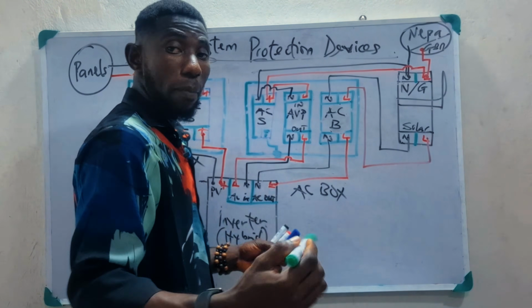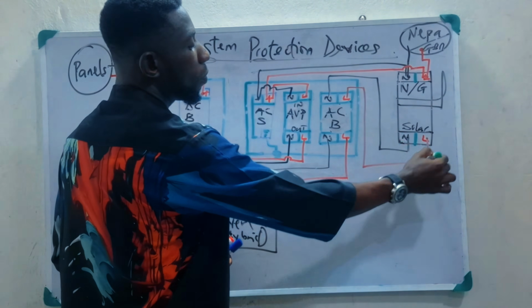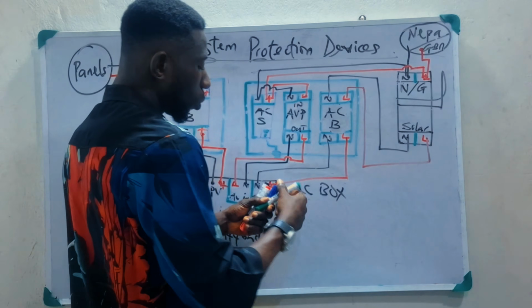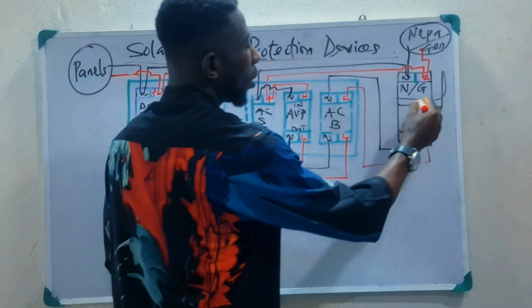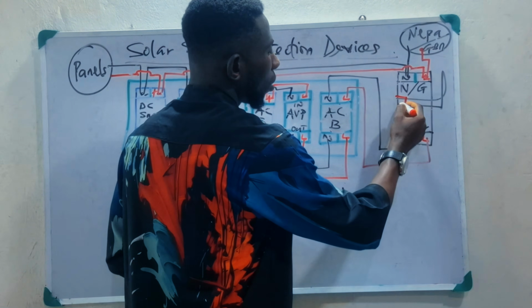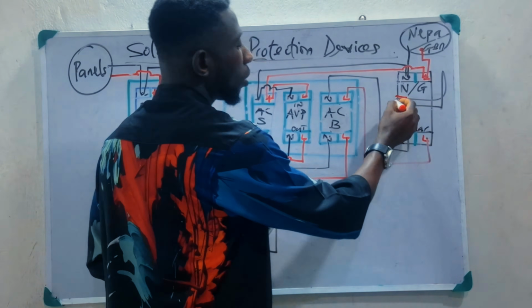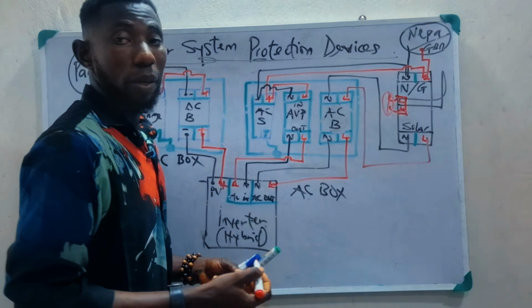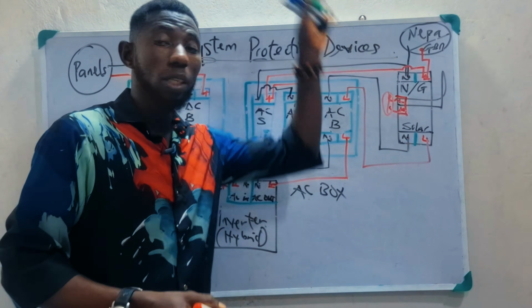then we bring a cable, we connect it from the up, and it comes and feeds the down part of our changeover to give us output. The output of the changeover is somewhere here: live, neutral, and this output is being connected to the house or the DB. Let's say the output is being fed to the DB.